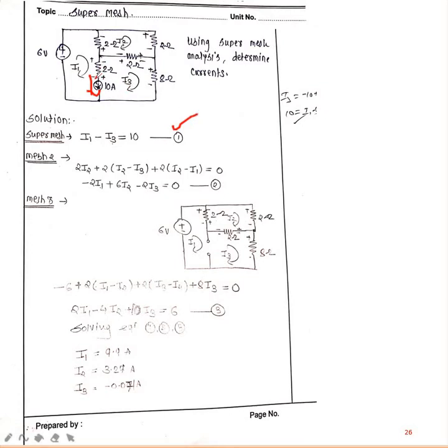After that, remove it, make it an open circuit. So this 10 and this 2 are also open, remove it. Then you will get this circuit. Here, how many closed loops? This is one closed loop. Write the equations. Here is another closed loop. This 2 belongs to I1, this 2 belongs to I3, and this 8 belongs to I3. Then write the equations, 1, 2, 3 equations. Then you will get I1, I2, I3, over.